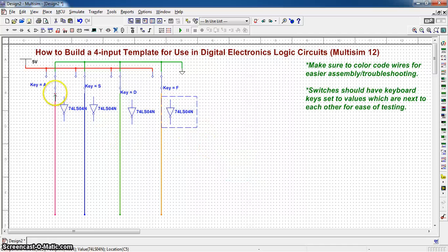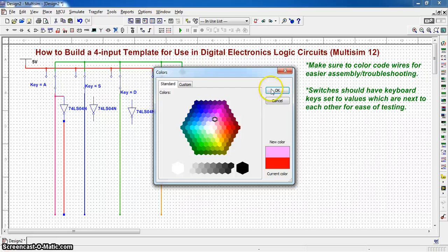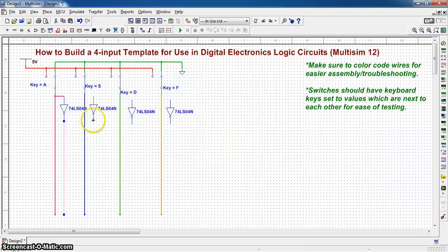Now what I'd like to do is, since the input wires simply give me my regular input value, let's say my value is called A, by taking that value and placing it through an inverter, I'm creating a value called not A. So I'm going to click and drag and double click again to place my wire. Notice I now have 2 wires running parallel to each other. And I'm going to change the color here so it's a lighter version of the color I have, so that way I have related in my mind as well as in my circuit. Makes it much easier to recognize later on when connecting components.